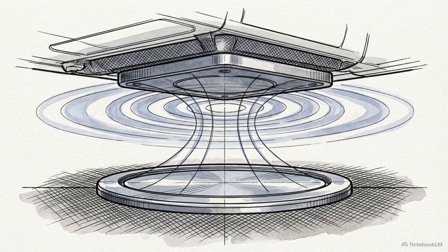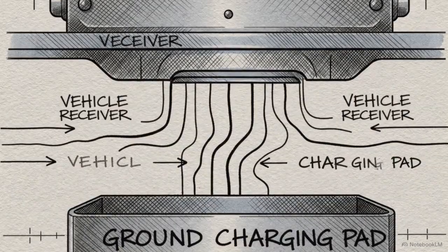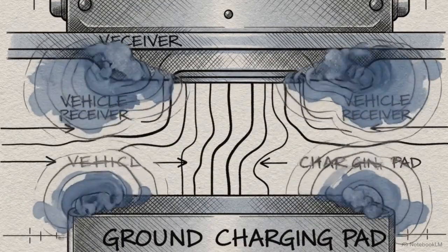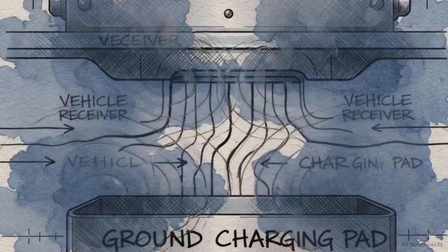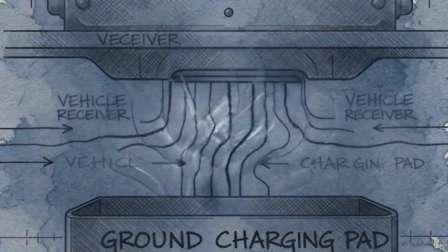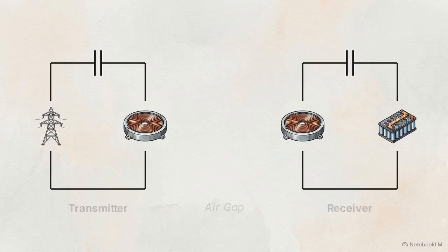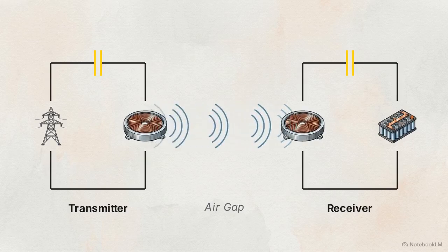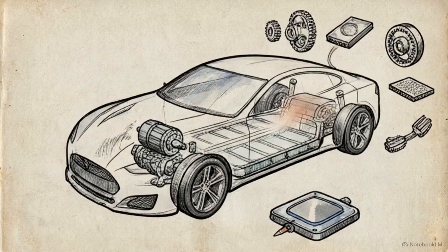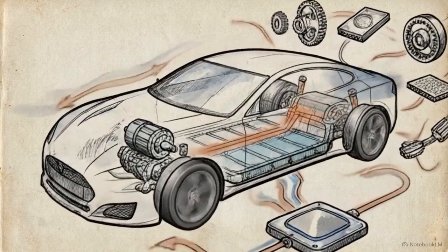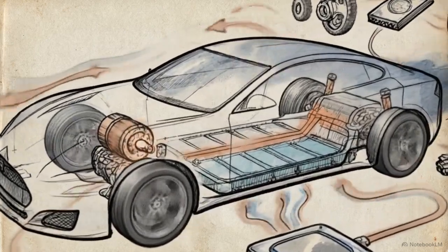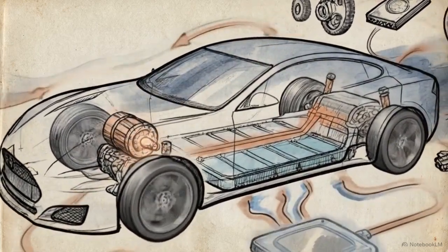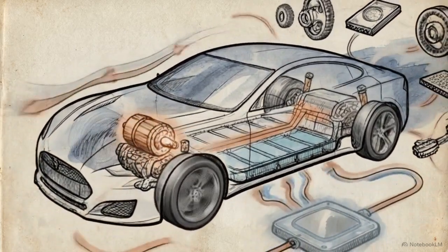Advanced grid interfaces include stationary contactless inductive charging. Inductive charging must overcome the physical challenge of transferring high power efficiently across an air gap without significant energy loss. This circuit schematic illustrates how resonant and compensation circuit topologies on both the transmitter and receiver coils allow for efficient power transfer through magnetic resonance. From mechanical friction on the tires to the magnetic resonance of the charging pad, a modern EV functions as a unified, continuously optimized electromechanical loop.